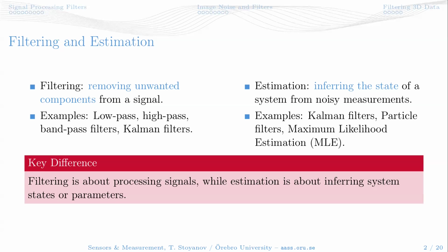So a typical example here in robotics would be estimating the pose of the robot relative to a reference frame. And we're going to use this example throughout when we talk about estimation, and we'll pose it a couple of different ways that we can do this. Kalman filters is one of the ways. Particle filter is another example. And then we'll talk a little bit about maximum likelihood estimation and expectation optimization, how it works.